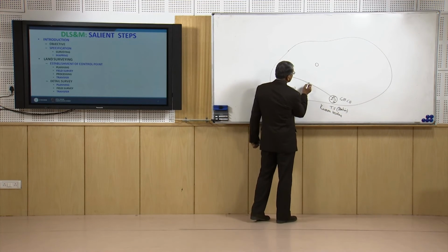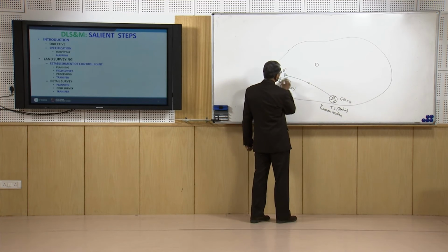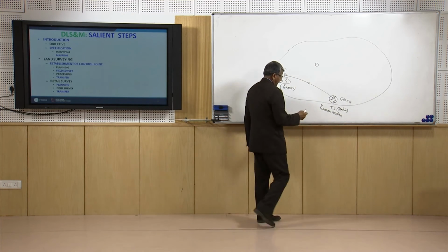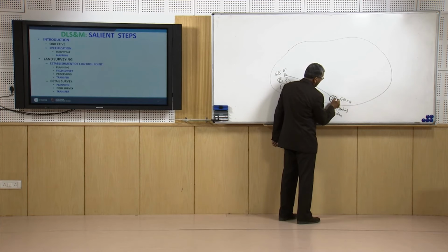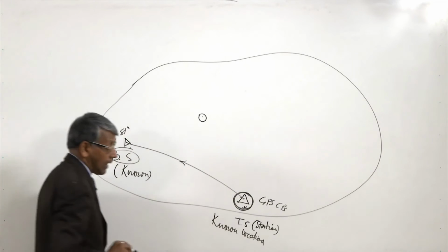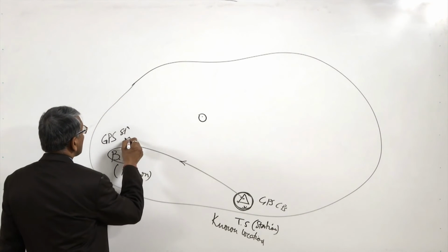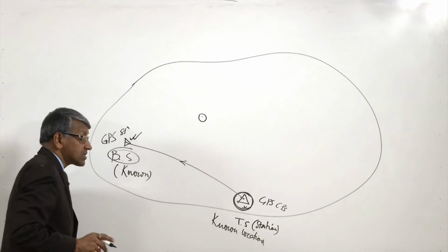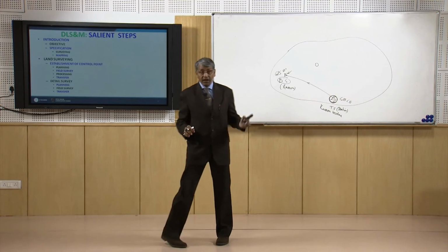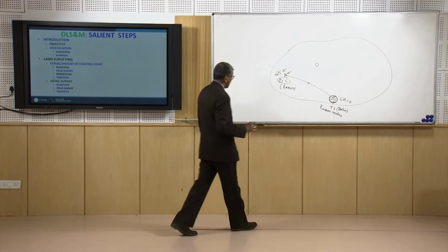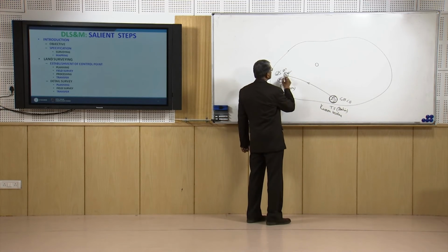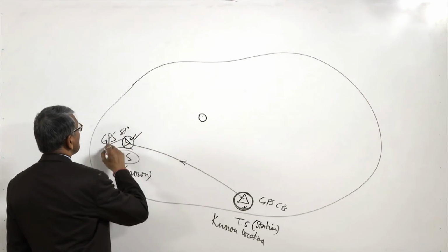That is called backsighting. This is the backsight station, so backsighting. So we will set up the total station on a point whose location is known. This we will find out by making use of GPS in digital land surveying and mapping. Then we will take a backsight to a station whose coordinate is known. That point is also a location whose location has been found out by GPS surveying.